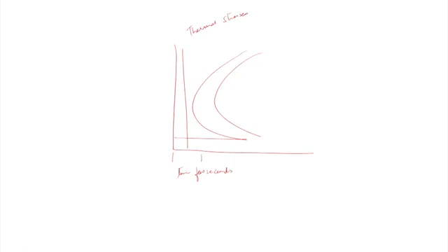Now, we have understood that all this kinetics is because of diffusion processes, austenite transforming into pearlite, austenite transforming into ferrite, and so on. So, if by any means I can reduce the diffusion process, or make the diffusion slow, I can shift the nose towards the right.